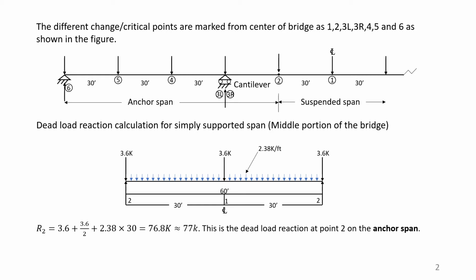These are 30 feet apart, but in a real case, when you will be designing a real bridge for construction, at that stage you will be taking 10 foot gaps, and there will be many more points for calculation and changing the reinforcement and the depth of the beam. Here, as we are just practicing a bridge, we have taken these gaps a little more than the standard one to minimize the calculation. From now on we will be noting the positions 1, 2, 3, 4, 5, 6 and calculating values for moment, shear, reinforcement, all these things. We will not touch the other points.